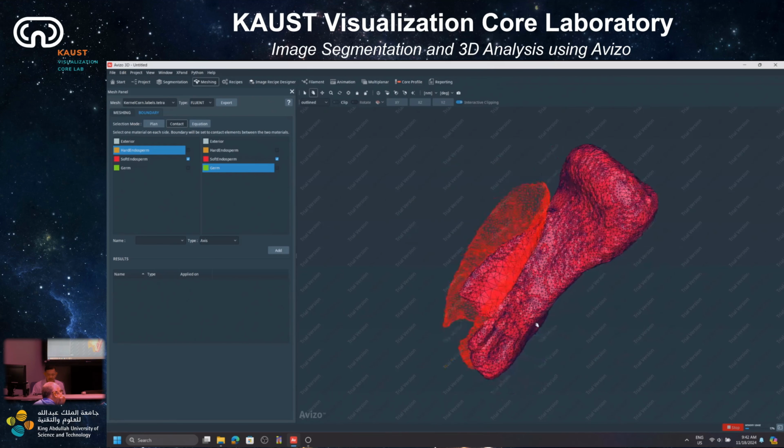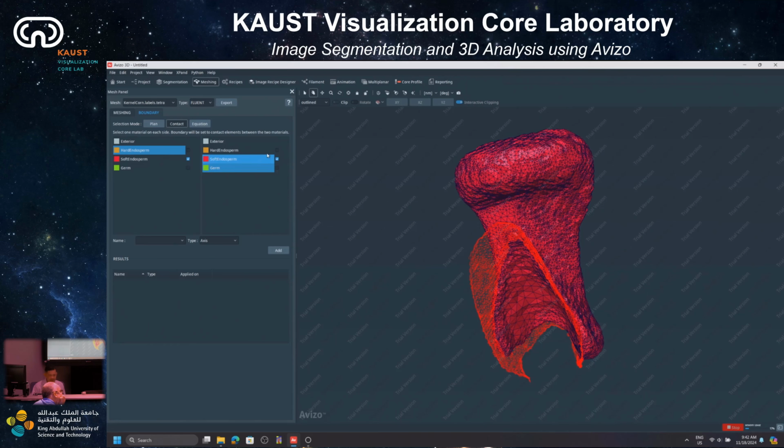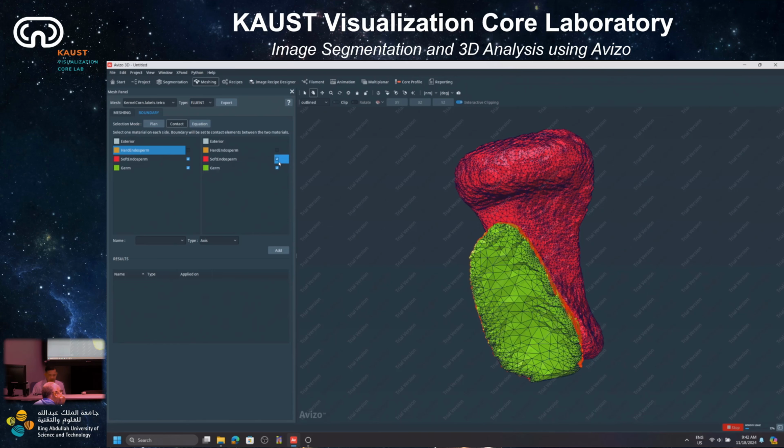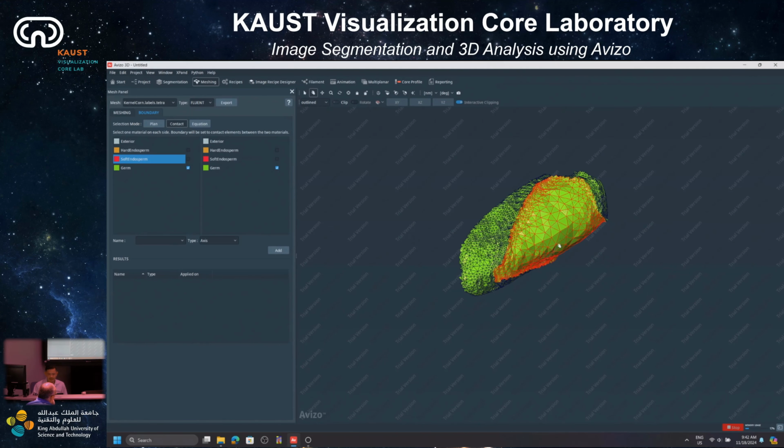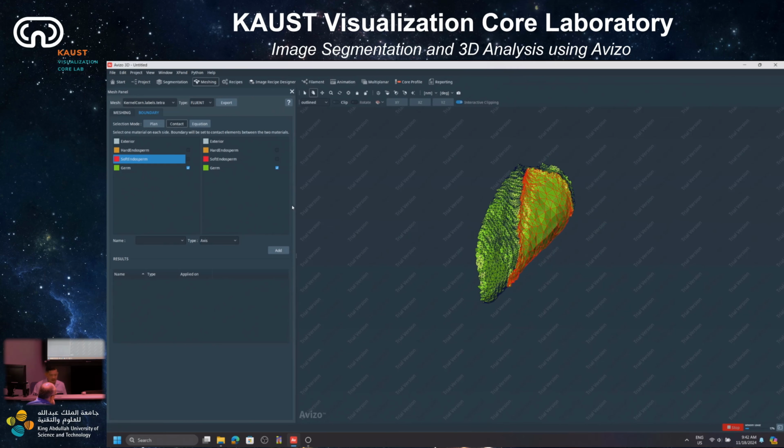So I have several contact boundary conditions. And yeah, okay. So what I want to do now, we're going to export this boundary condition together with the mesh. So you just have to decide which boundary condition you actually want to export. So maybe I want to export this boundary condition. And to do that, I just need to select the name.